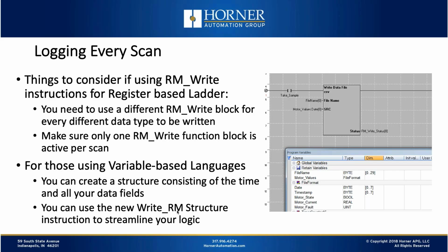That's important as well. For those of you who are using variable-based languages, whether you're talking about advanced ladder with variables, or advanced ladder with tags as it's sometimes called, or if you're using our IEC package, we have a new feature we've added recently. I believe we added it in Service Pack 3, which effectively allows you to utilize a structure for all the data that you're going to be logging or writing to the removable memory card.